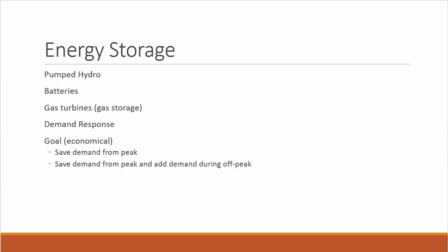Now this is something we don't like to do in electric energy. When you reduce the peak without moving the demand to another period, you have lost income. And this is why many demand response programs are not desired, because they reduce the end use of electric energy, which is not a goal for either the utility or for most consumers.